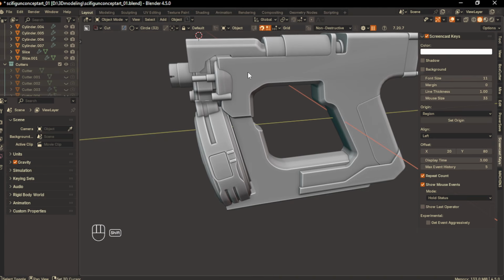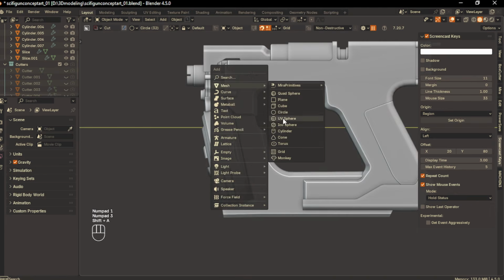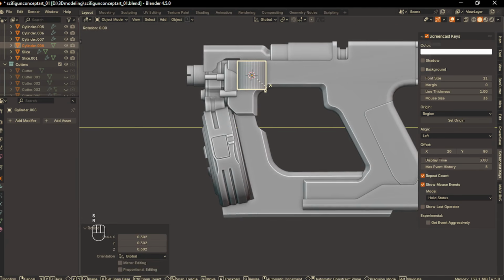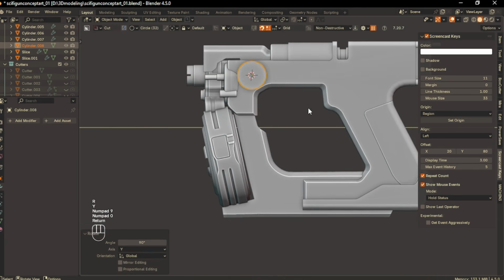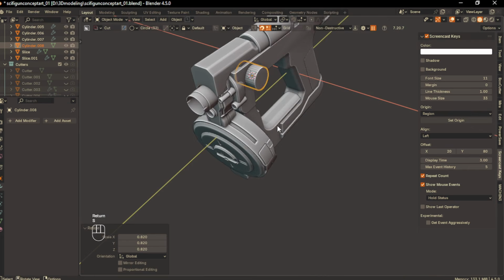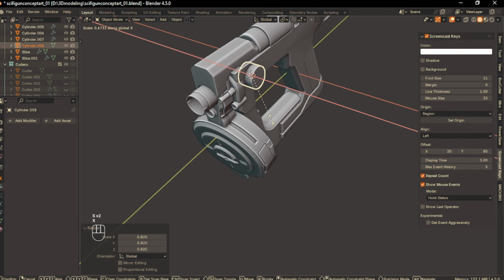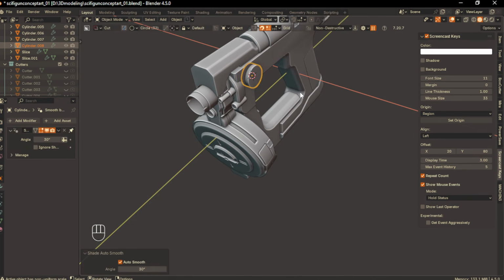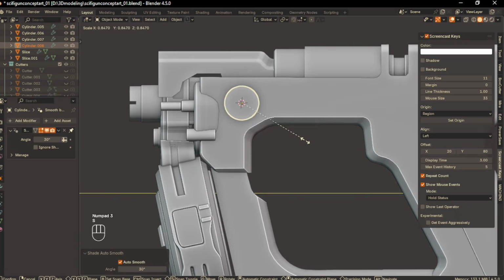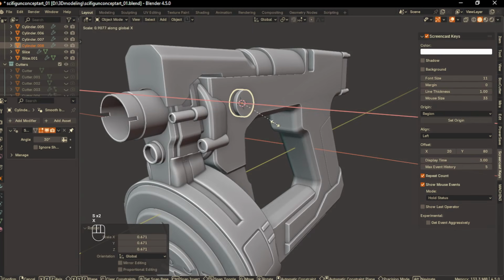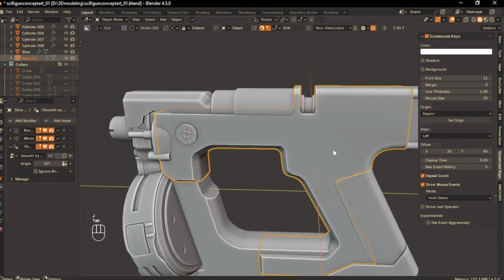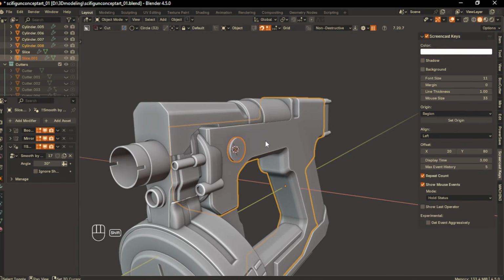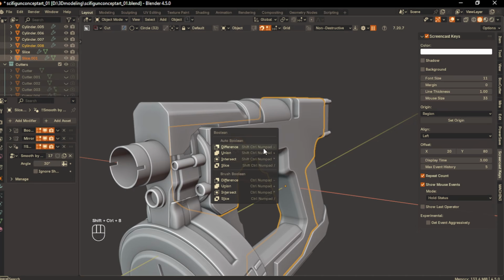Now, I'm going to stack some additional mesh. First, I'll place the cursor here and add a cylinder, scale it down like this, then flip it on the Y and scale it even smaller, adjust it on the X-axis, yep, like that. Make it smaller again and just fine adjustment. Next, we are going to join both objects. Select them and run a union boolean.